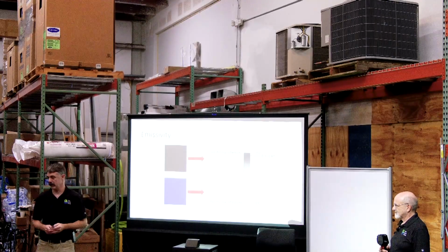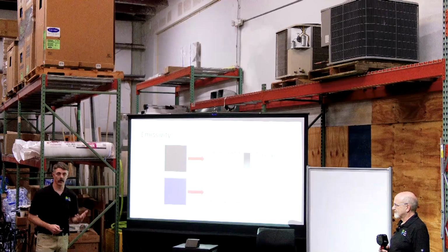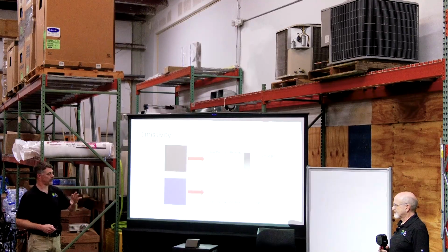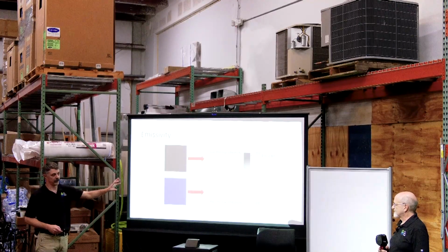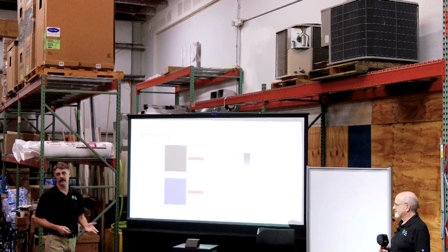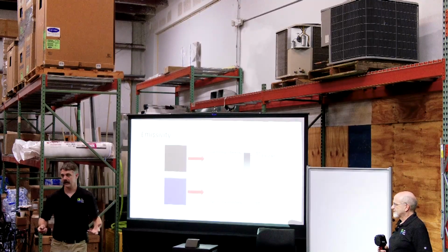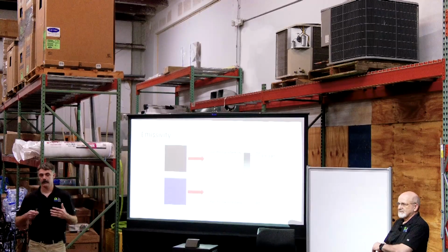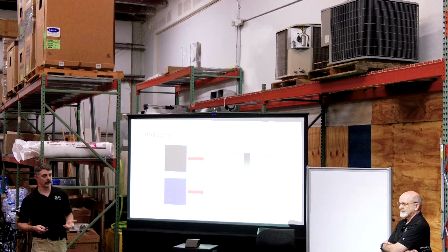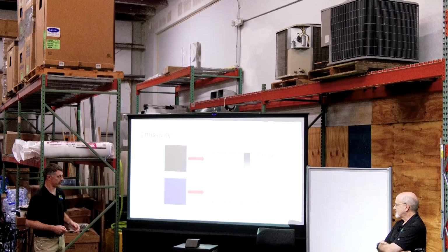If you need a better quantitative measurement, a more accurate measurement on there, you want to be a little more precise, go in and adjust that. And you can find emissivity tables online. I don't have any to just give you right now, but find them online. They're readily available. They're downloadable in a PDF. Free for everybody out there.